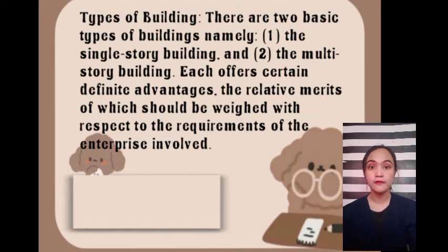First, greater ease of expansion through extension to the existing building is made possible. Second, there is less vibration where sensitive equipment and material are employed together with heavy machinery. And third, the soil requirements for the foundation are less severe.